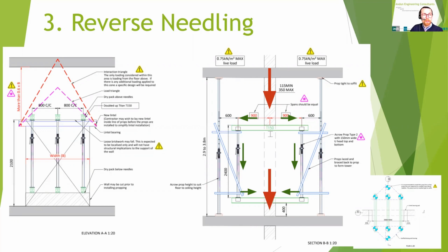The propping from the floor to the ceiling, that's shown, that's outside the needle props. They're used so that the propping has got something to brace back to for lateral stability. A tall prop such as this is not required on every prop. Here we've got just 1 per 3. It's just there so we can brace back to something and make sure we maintain that lateral stability.